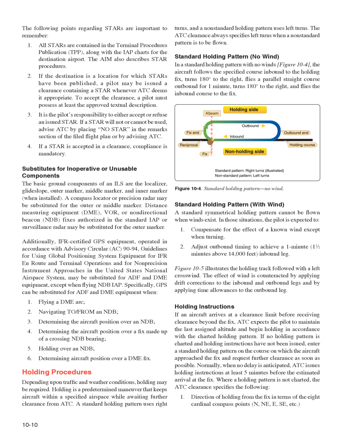The effect of wind is counteracted by applying drift corrections to the inbound and outbound legs and by applying time allowances to the outbound leg.